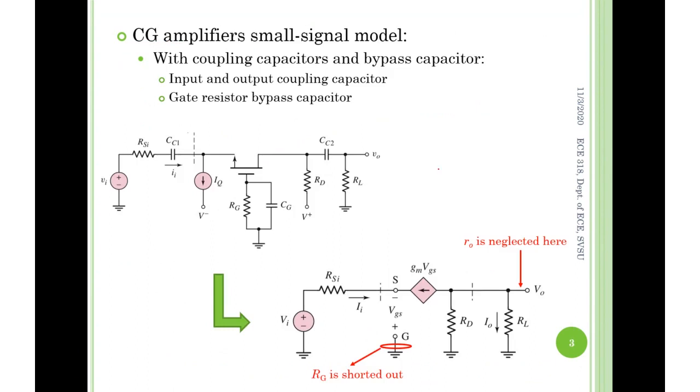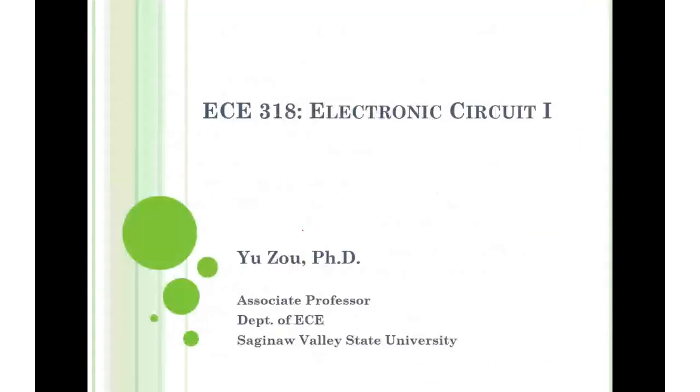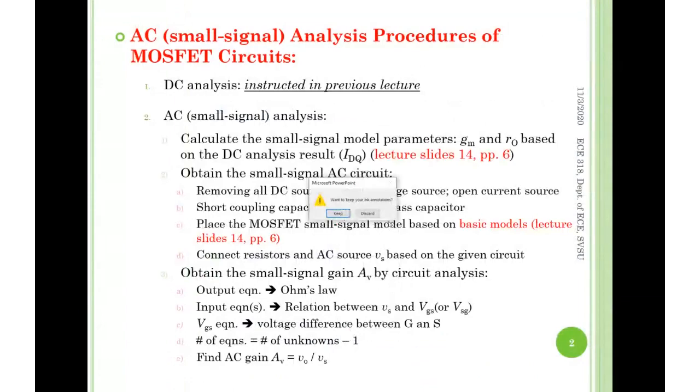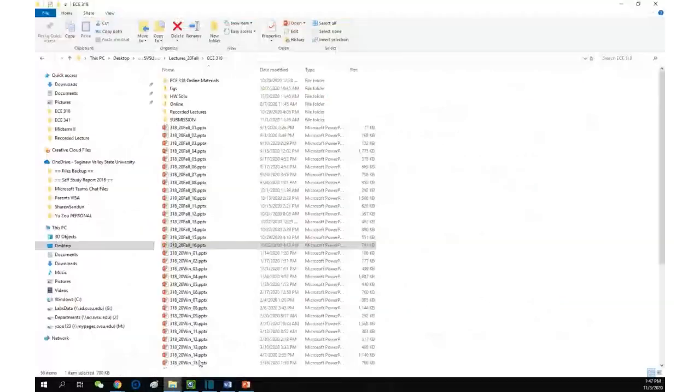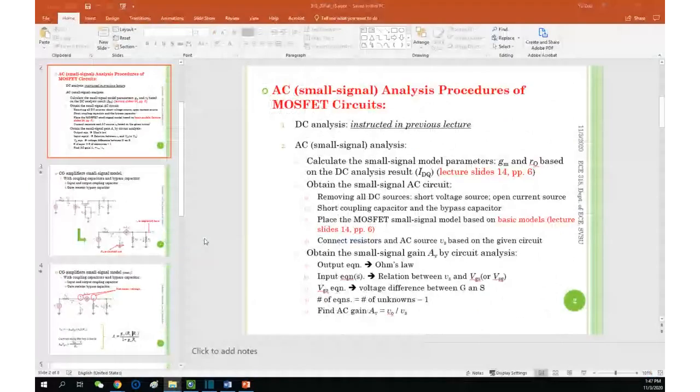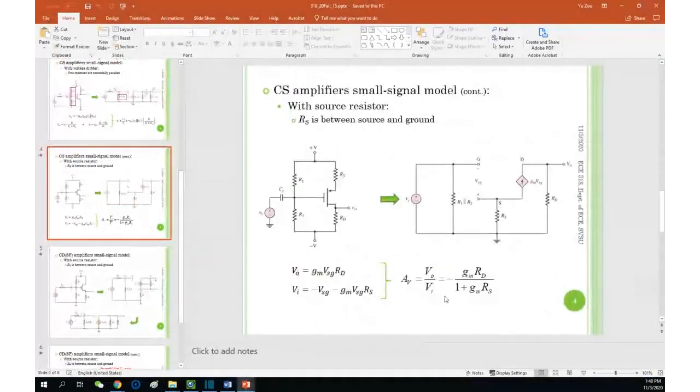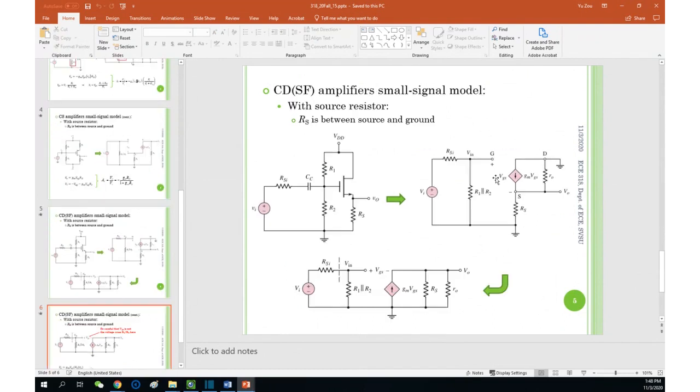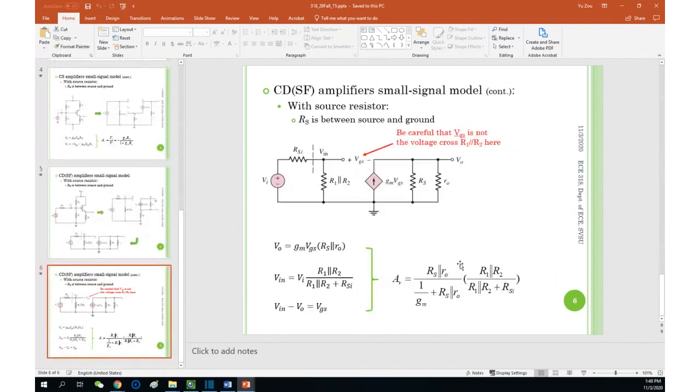Same thing here. The common drain, last lecture, and the common source, right? Common drain and common source. This is a common source. Does the common source voltage gain follow this formula? No. Okay. This is the result for this particular circuit. Don't try to memorize these formulas. They won't work. This result is the common drain voltage gain formula? No. Absolutely not.